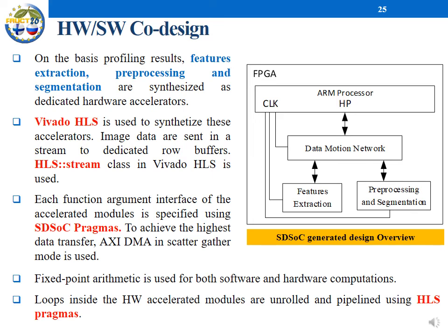Each function argument interface of the accelerated modules is specified using SDSoC pragmas to achieve the highest data transfer. AXI DMA in scatter gather mode is used. Fixed point arithmetic is used for both software and hardware computations. Loops inside the hardware accelerated modules are unrolled and pipelined using HLS pragmas.